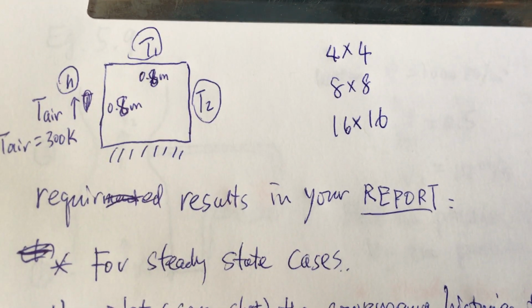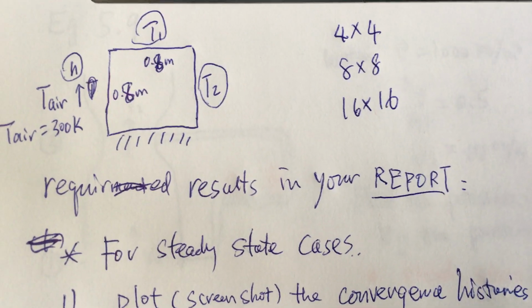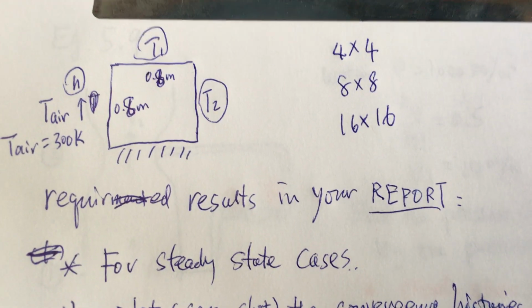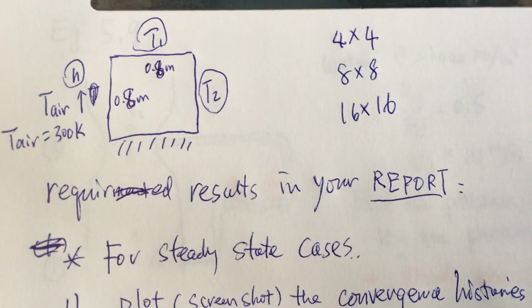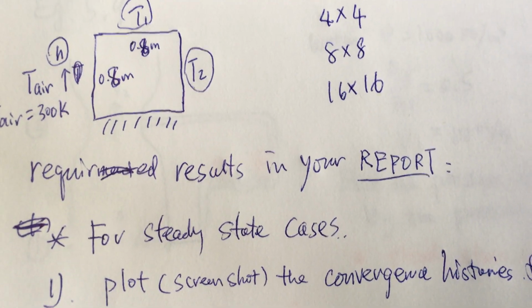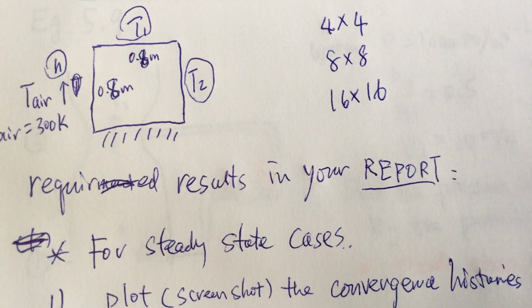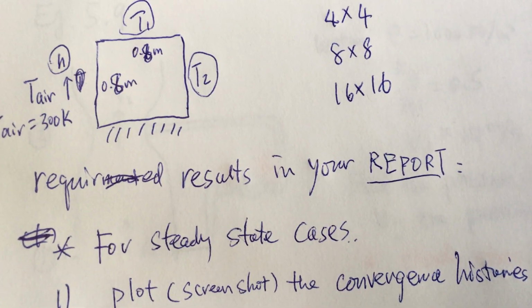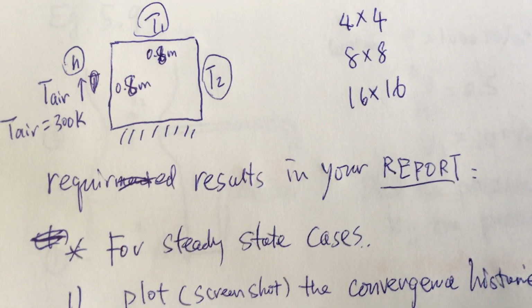You can calculate a maximum relative error inside the domain on every point. So that residual is the maximum relative error compared to the previous iteration. When the relative error reaches 0, that means the result is converged. You add more iterations, it won't change, right? There are no relative errors. So then we say it converged.